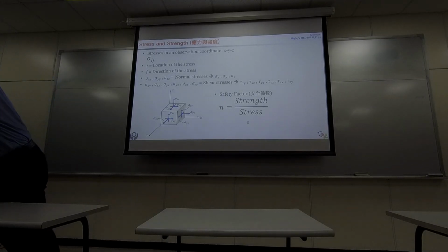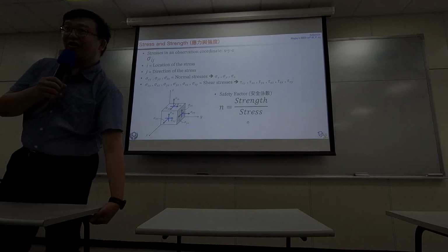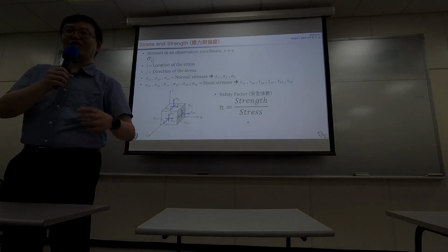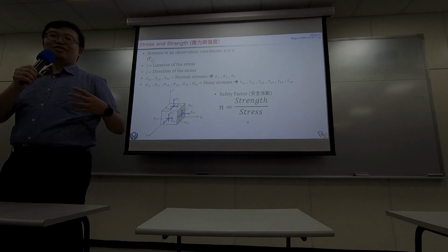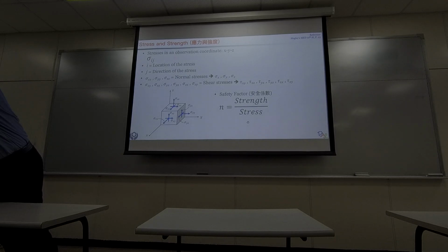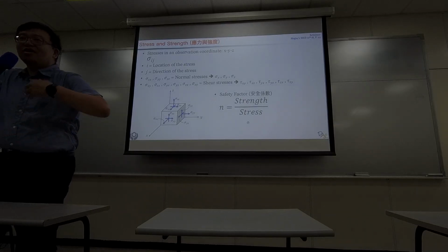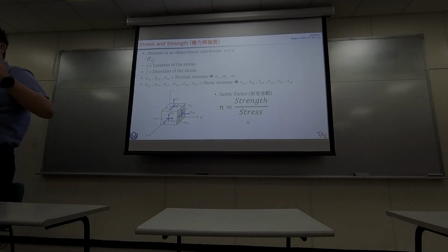If I apply a strong force like this, maybe some bolt right there cannot carry the load anymore. One day the bolt will crack. This is the so-called static load. The force doesn't change with time if I just apply a force like this. But there's a different kind of load, like this, fluctuating. The force changes with time.